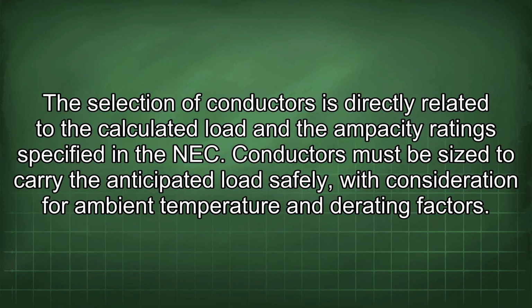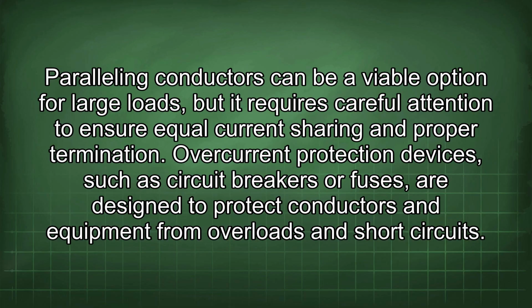The selection of conductors is directly related to the calculated load and the ampacity rating specified in the NEC. Conductors must be sized to carry the anticipated load safely with consideration for ambient temperature and derating factors. Paralleling conductors can be a viable option for large loads, but it requires careful attention to ensure equal current sharing and proper termination.